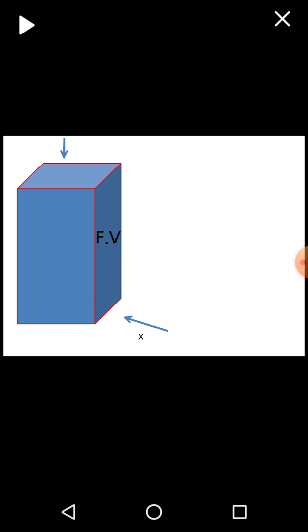Now next, the observer position will be changed. Now the observer is looking from the top direction and will get a square as the projection in the top view. Next, if we are standing in the x direction, the side opening of the object is on the left side. The y direction is given here, and the y direction always shows the side view direction, and that is the left hand side view in this case.